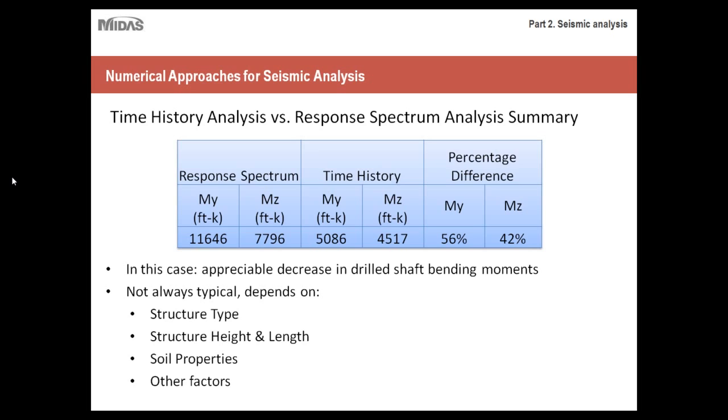So I'll review that quick point I made. With response spectrum analysis, the results will be more conservative, because you're making more assumptions and taking fewer variables into account. Whereas time history analysis takes longer because the level of analysis is higher. There are more variables taken into account. It's less conservative and more optimized. So there's that trade-off. It really depends on the type of region you're working in as well as the scope of your project, which type of analysis you would run. But just keep that principle in mind.